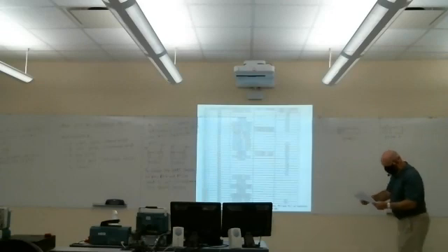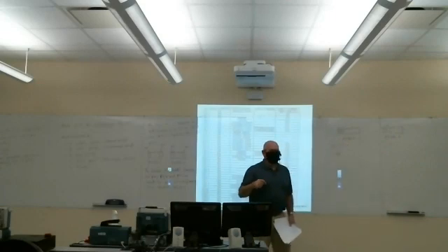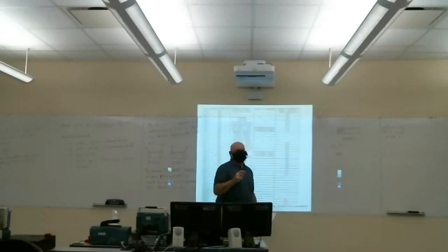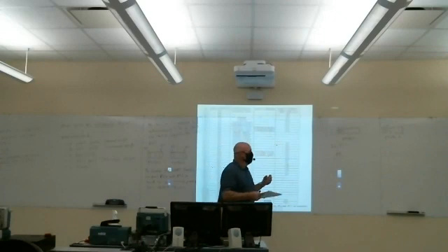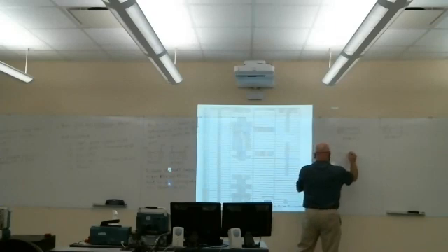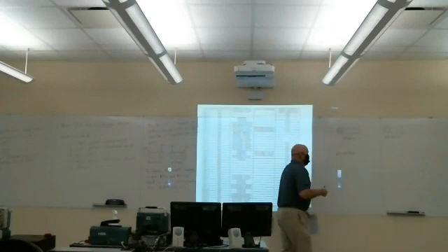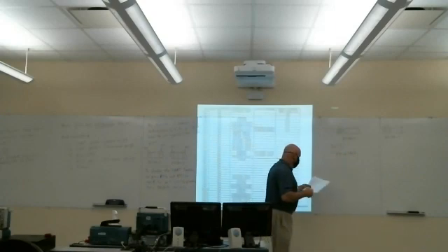So one way to do that in C is that P9 is actually defined in this header file with its particular address. So we don't actually have to dig through the manual and find out what the register address is for this P9 register. But it's a pointer to a structure, actually. Again, we'll look at this in a lot more detail. You can find the corresponding address. We can find the definition of that structure.